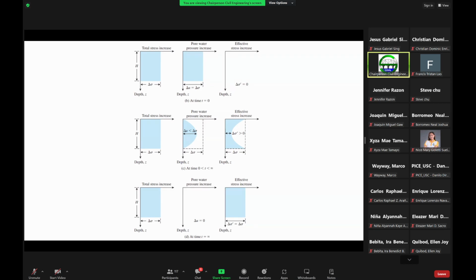I think in my experience, we have calculated consolidation settlement as deep as say, around 300 millimeters. That's about 30 inches, or about one ruler. So you can just imagine if you have a house, and your house will settle by about 300 millimeters. Then your door is opening outward. Then yes, you cannot open your door. You cannot enter your house.